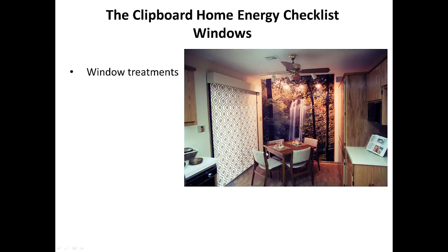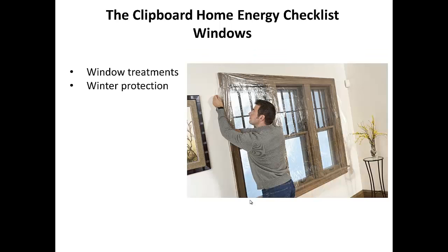I remember how I said that radiant heat from a wood-burning stove makes you feel comfortable. Well, this is a cold surface on a 10-degree day, and if you're sitting in that chair, what your body is doing is radiating heat, and that cold surface says, give me all the heat you can because I want it. And your body will feel cold because the radiant heat from your body is literally being sucked to that cold surface. So having something between you and that cold surface is going to help your body feel more comfortable and your furnace work not as hard.